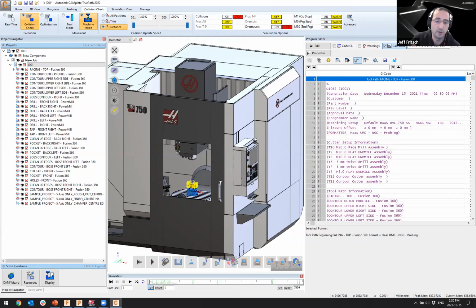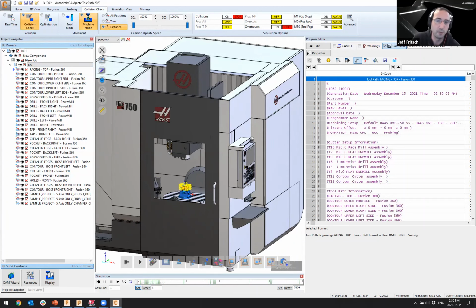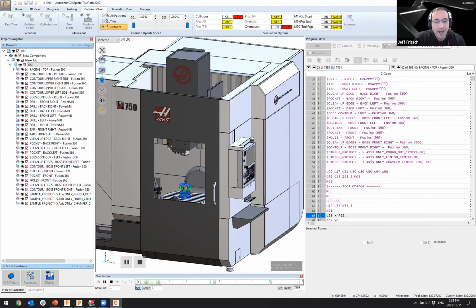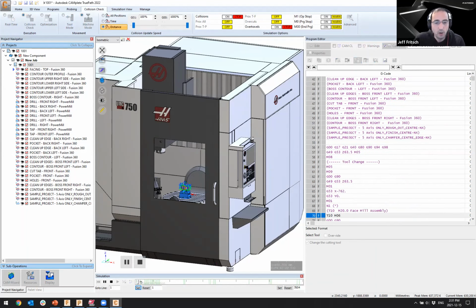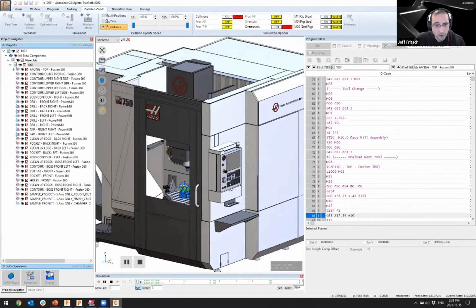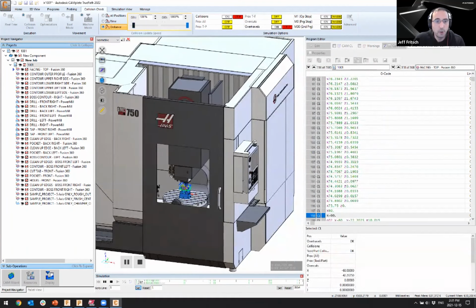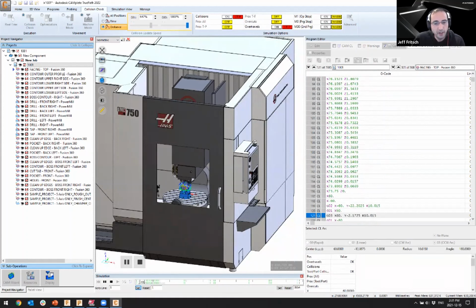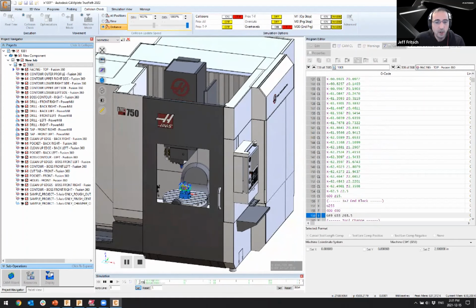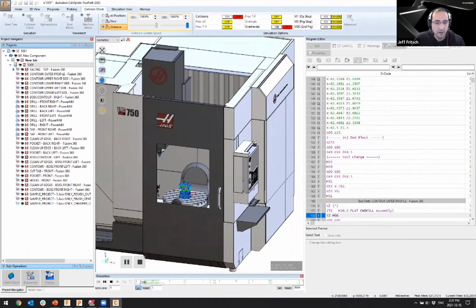Can the machine tool actually handle this code the way it was actually produced? So we'll be, of course, looking for collisions, for over travels, for overcuts. So if we have any type of gouges into the parts. If we wanted to look at particular proximity elements, so between the tool, the fixture, the part, there's a number of ways we can really start adding particular elements that we want to check. And then of course, full tool change approach, and then at that point verifying that really the machine tool can actually handle the motion the way it was defined in the CAM system.